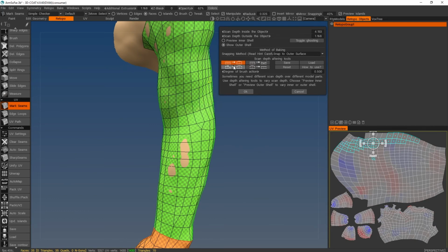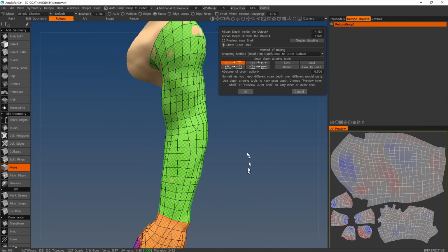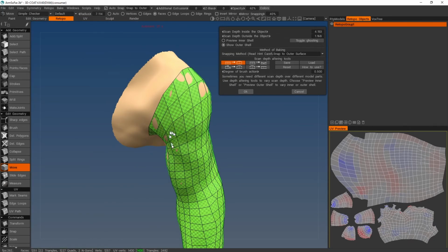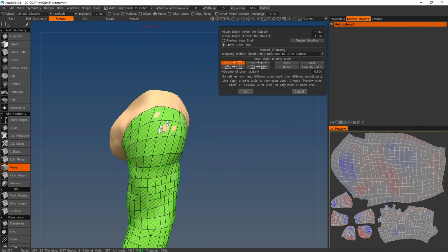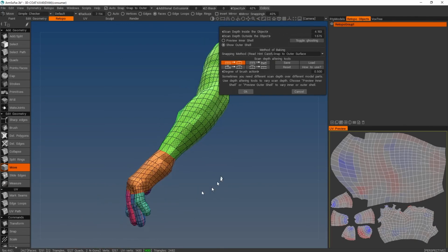So these buttons here push and pull the mesh so that you can move the cage in different ways. So with this one, we can increase the depth of scaling. So I can just go in and I should be able to paint, but I'm moving only the vertices that I'm painting. So I can go around and push these out. If you want a general solution, you've got the inside and the outside depth, and if I just push the outside depth, the whole thing will push out. Just going to fix these bits here. Right. Okay, that looks fairly clean. There's a bit missing there.